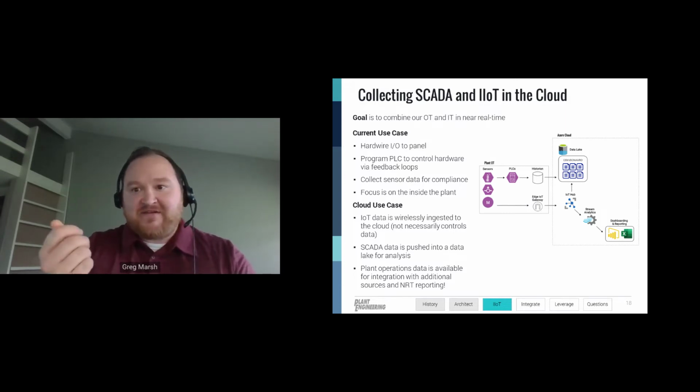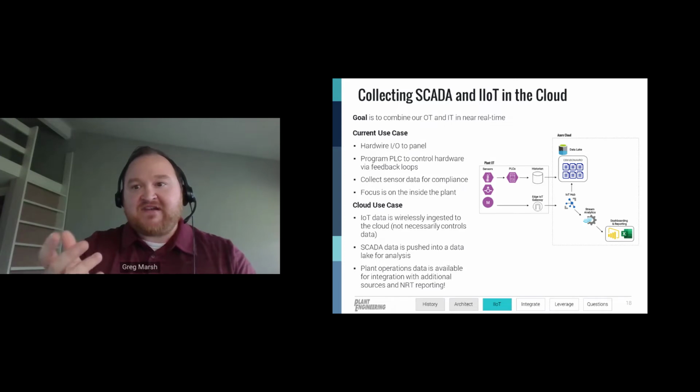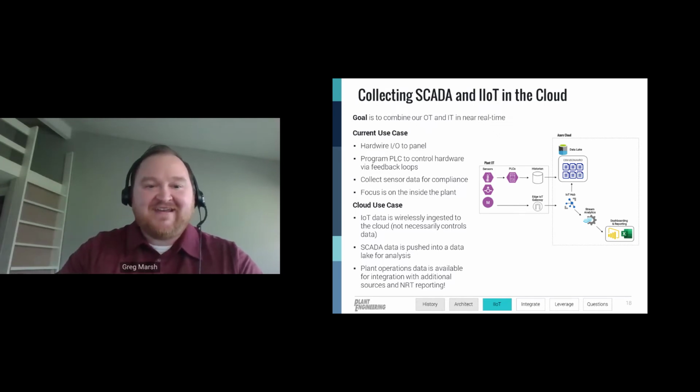So just a couple things I wanted to mention about this. Hardware is really coming along with this. A lot of it comes with Ethernet, 4G, 5G transmitters almost as standard. And this is to allow us to connect our information directly to the internet. But again, to bring it back to what I mentioned earlier, I don't see these as controlled devices necessarily. I don't see the cloud as a replacement for a PLC anytime soon. And it really comes down, for me, to latency.